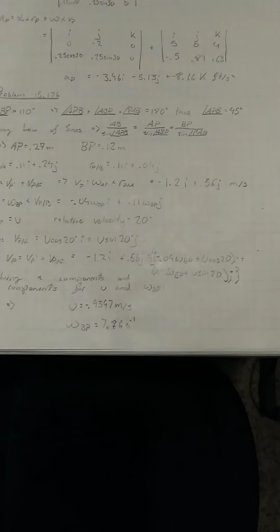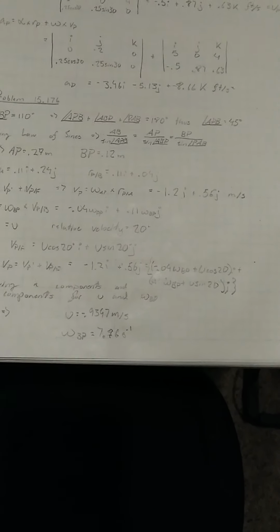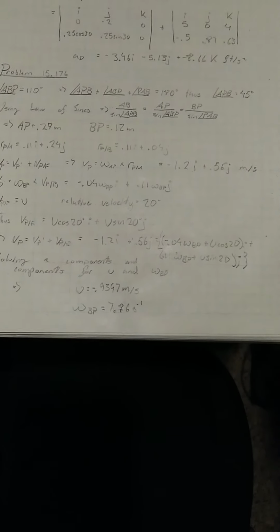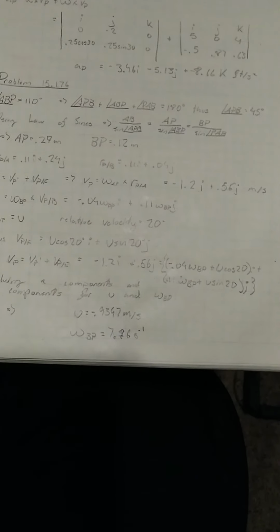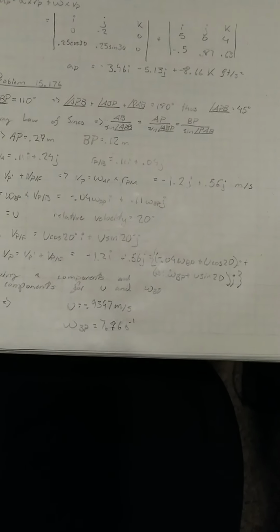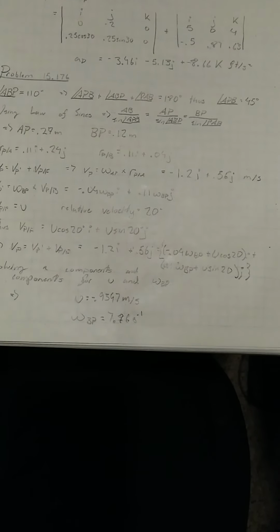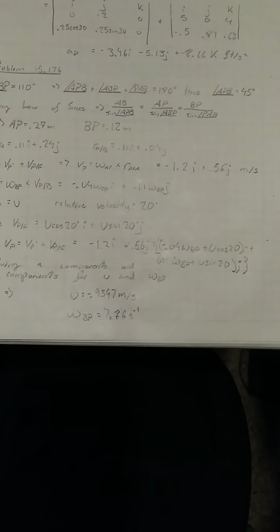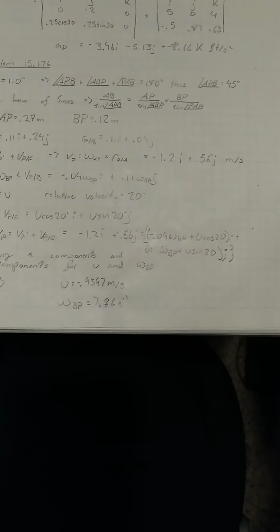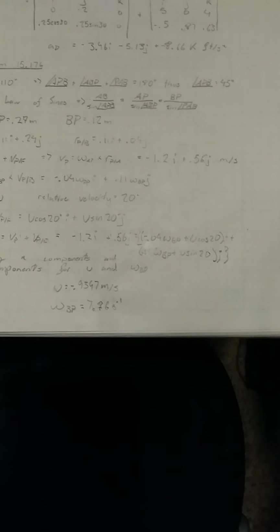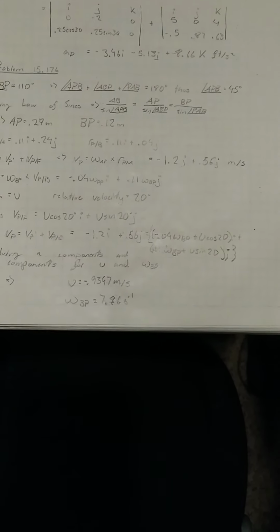And then we've got to think about the unit vectors along the x and y directions, with the angular direction in k. So we know that link AP is at an angle of 25 degrees, and so the coordinates of the point P with A as a reference are 0.11i plus 0.24j, and the link BP is at an angle of 70 degrees. So we take the point B as a reference, and we find that position vector r sub P over B is 0.11i plus 0.04j.